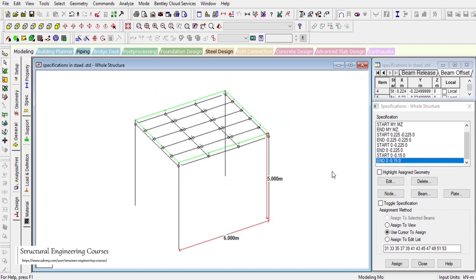There's one more thing that I'd like to add here, because in structural steel members we also have bracings. So how we can add the brace is that we can just left click on add beam, and left click here, and then left click here again. Similarly we need to model a bracing from this point to this point. So how can we make sure that this member will only take compression, or only tension, or can only behave in a particular manner?